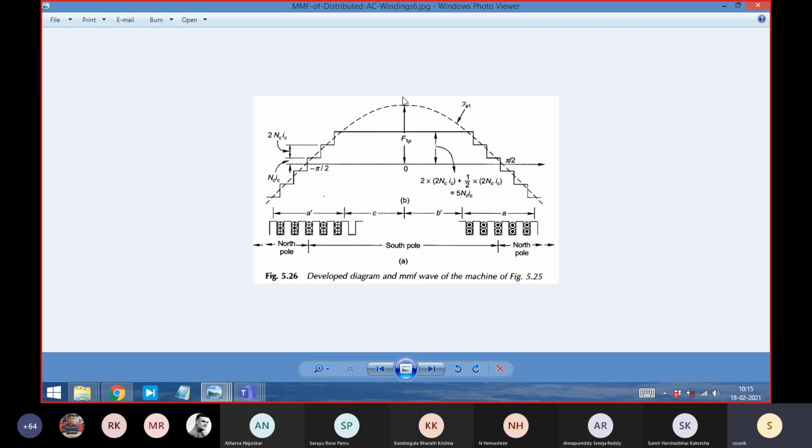Okay, three phase currents are created in the rotor, and the rotor is also producing a magnetic field, and that magnetic field is rotating with respect to whom? With respect to the rotor. Now, rotor may be having some speed. So the magnetic field created by the rotor has a speed with respect to the rotor that is proportional to the frequency of the voltage that is created inside the rotor, or the frequency of the current that is inside the rotor.